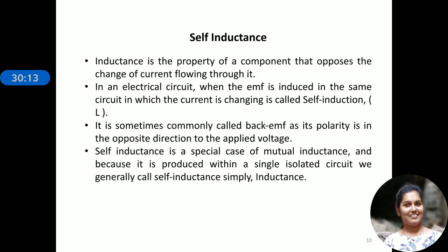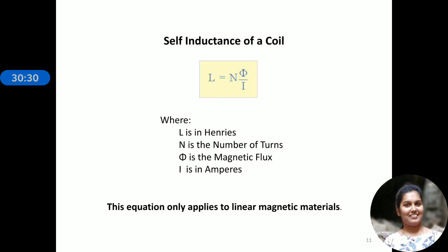Self-inductance is sometimes called back EMF also, as its polarity is in the opposite direction of the applied voltage. Okay. So here I have given you an expression relating L, N, phi and I. The point to be noted regarding this expression is that this equation applies only to linear magnetic materials.